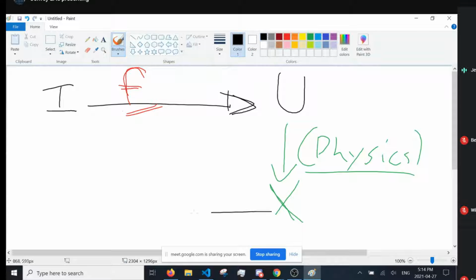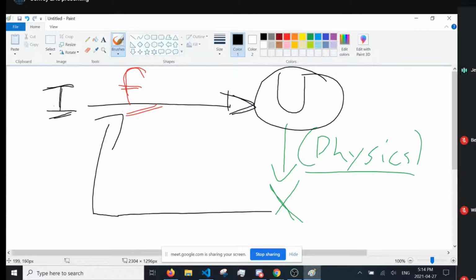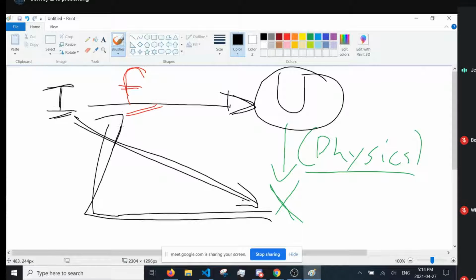We want to feed our state back into our robot actuation, and that way, instead of only being able to... with an open loop system we're not actually controlling our state, we're controlling our actuation points, right? But what we want to do is control our state. If there's an arrow from our inputs into our state, we want to actually control our state, however that's defined, and through a closed loop system that's how we're able to achieve that.